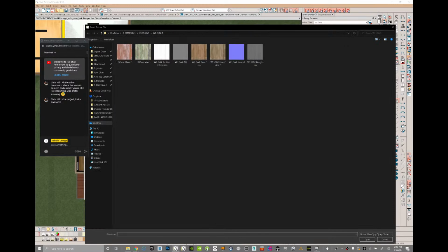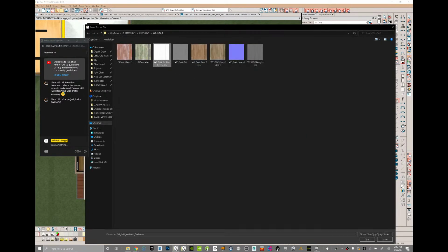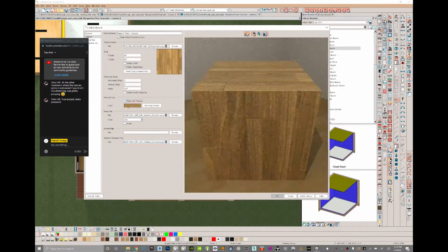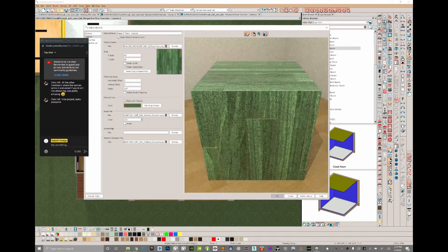Next is I'll put in a bump map, which in this case I just have my ambient occlusion map. I could actually put in a normal map, but we'll go ahead and stop that for now. We'll put in our ambient occlusion map, which helps for those scenarios when the scene is not properly lit. And the purpose of this particular diffuse channel map is for blend with texture. And it's so that you get the most realistic blending with texture, because otherwise it really doesn't look that good. So this enables us to do some funny things like making a dark green floor still look pretty good.